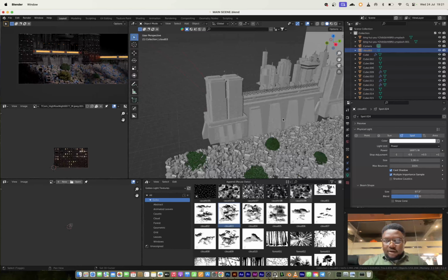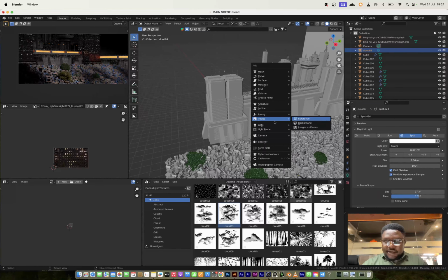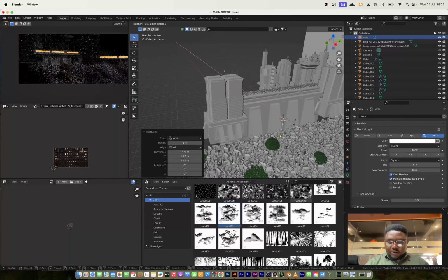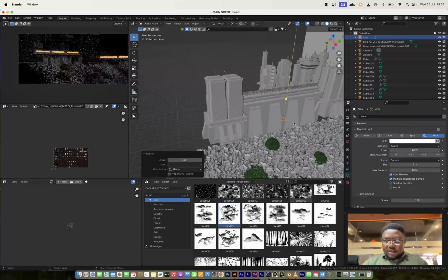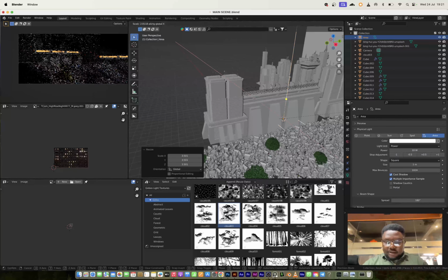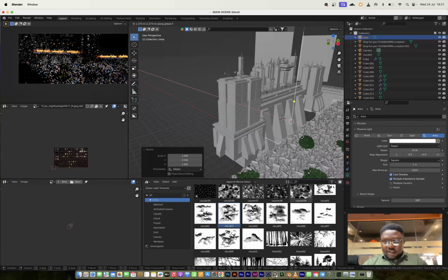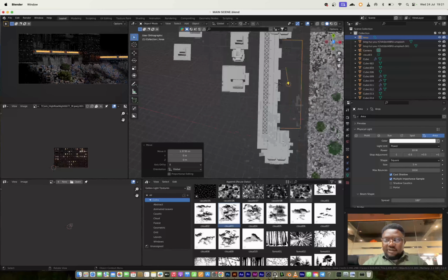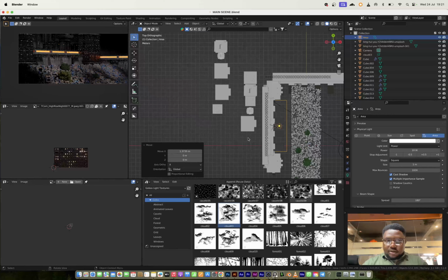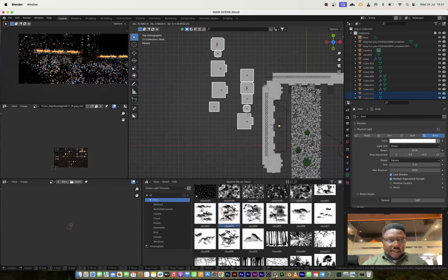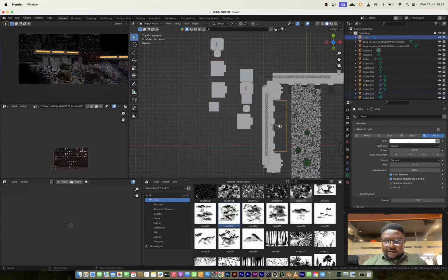Now I'm going to put a light here. Let's bring in an area light and rotate that on the Y by 180. I'm going to scale on the Y also, and move it on X. Let me not put one on this side first. I feel like this side should get a highlight first.